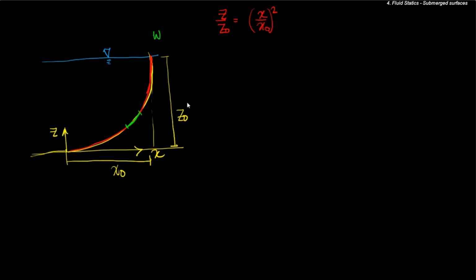So now if we consider this area, the force will act normal to the area. So this will be the direction of the pressure, and so the force at a given point dF will be p dA, which is essentially p times this arc length ds times the width, but this force is going to act in the n direction.